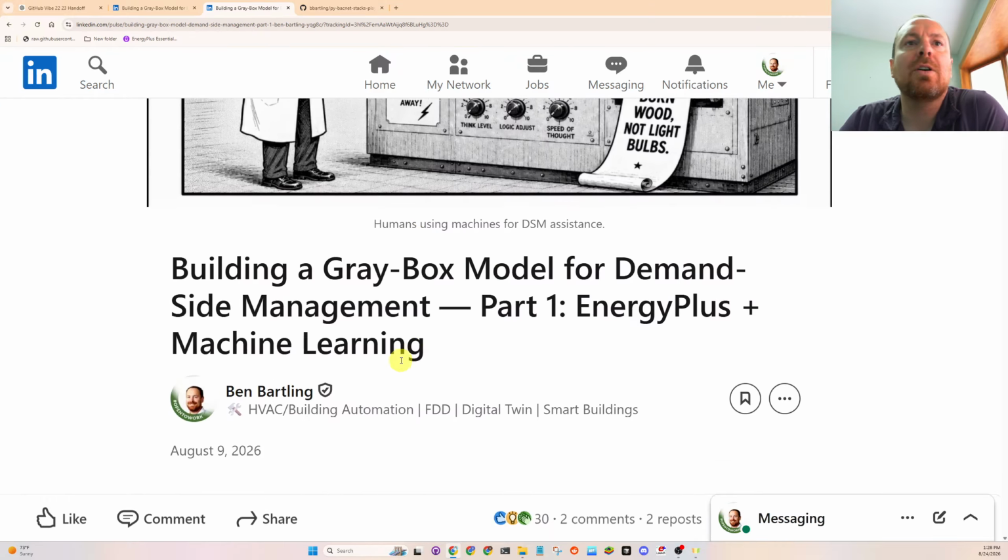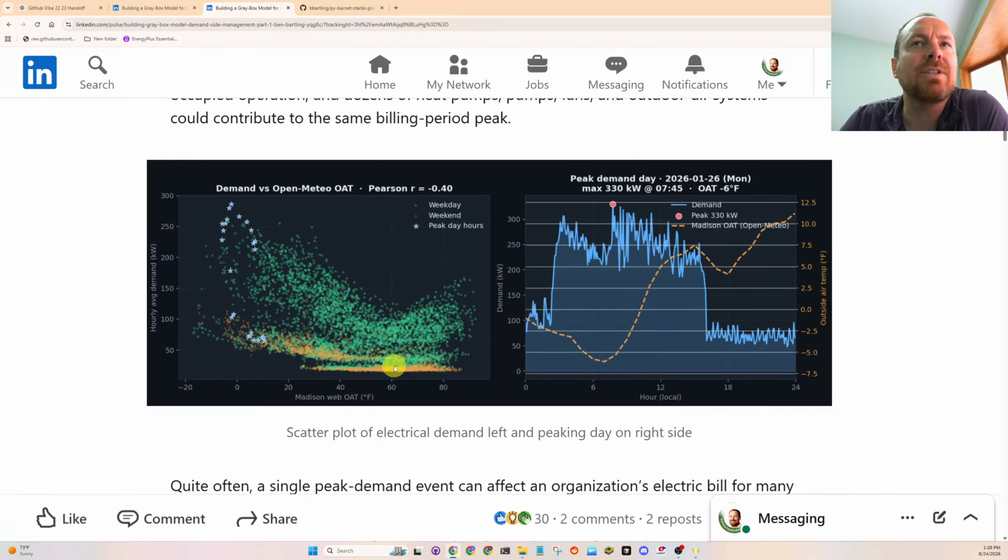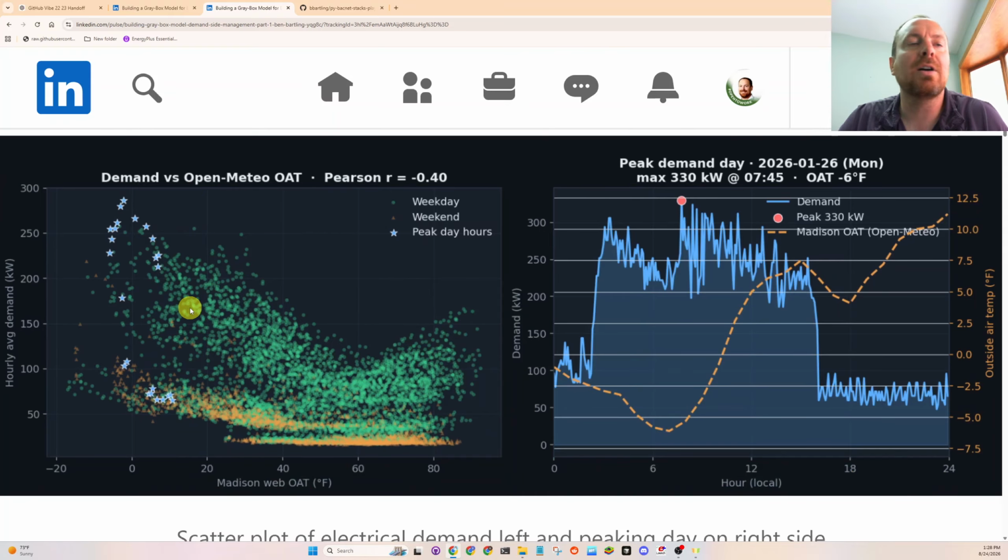Okay, so if I go down here, this is basically the electrical data right here. I looked at this a little bit before. See if I can zoom in or not. So this was the school's coldest morning. I think it was 10 below zero overnight in degrees Fahrenheit. They peak at 300 kW right when it starts up. And in this mild weather band right here, that is the lowest amount of electrical energy, lowest amount of electrical power required.